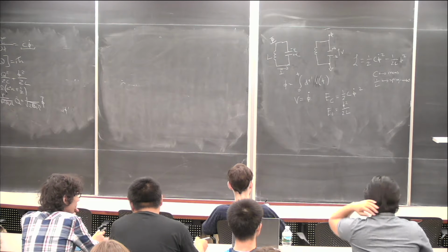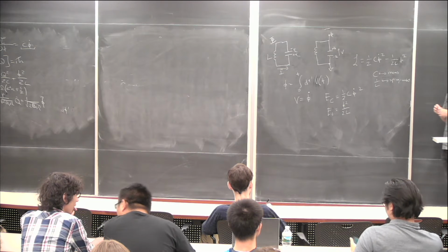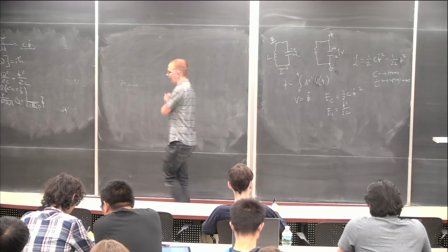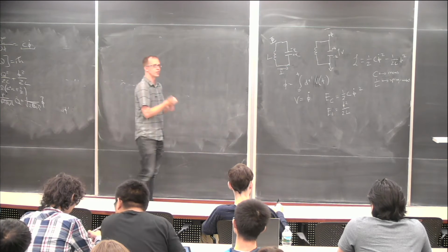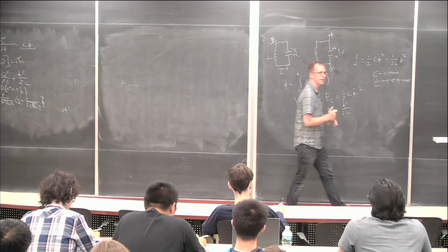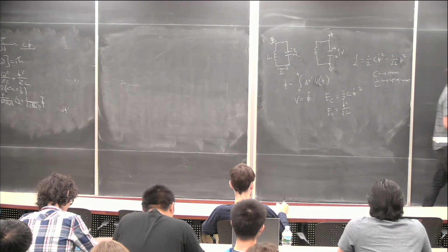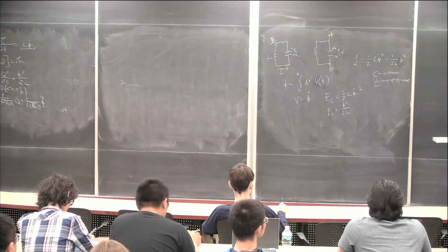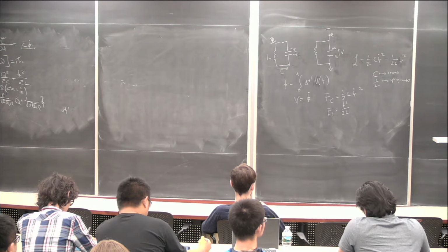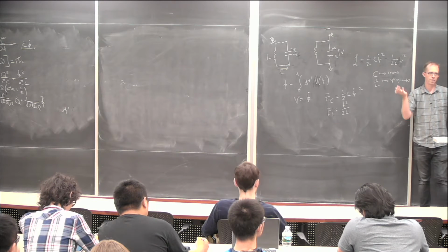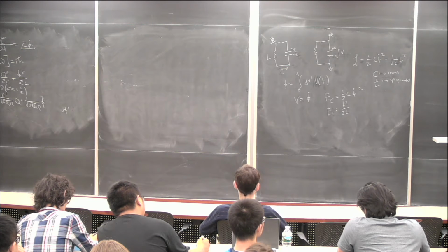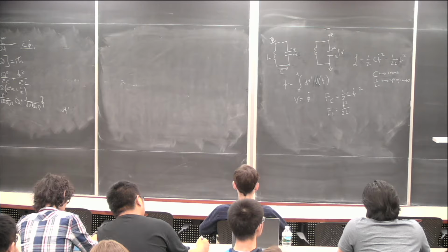Okay. In order to add anharmonicity to the circuit, we need something that is nonlinear. Fortunately, we have something nonlinear from the world of superconductivity, and that is a Josephson junction. A Josephson junction is a metal-insulator-metal sandwich, a tunnel junction, where on either side of the junction you have a superconductor with a well-defined phase. You can think about the phase difference across that junction, and you can write current and voltage characteristics for that junction.